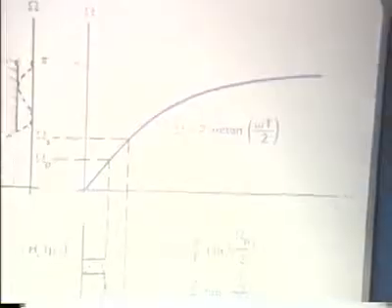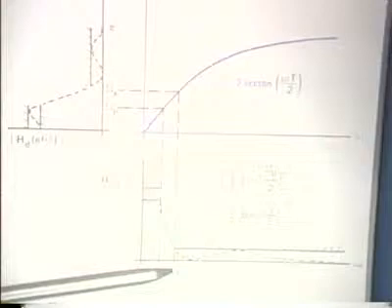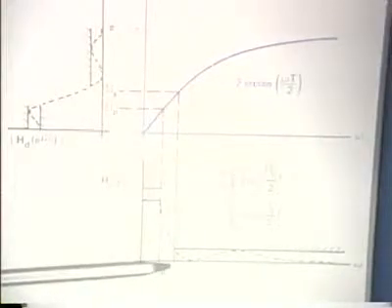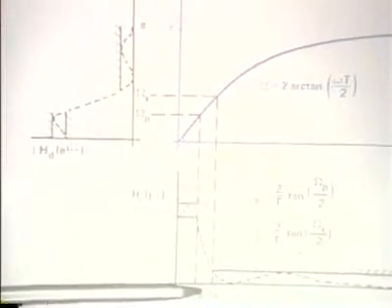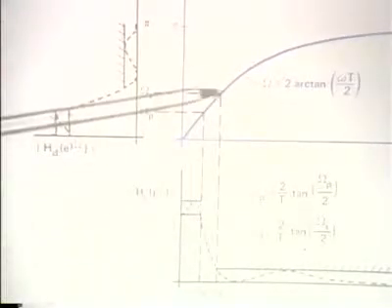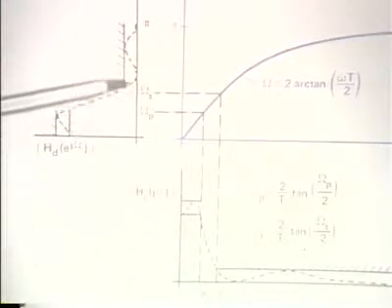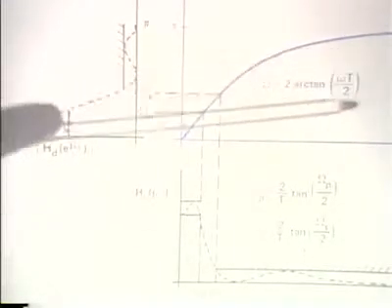So let's suppose that the continuous time frequency response looks as I've shown here, with a passband cutoff frequency and a stopband cutoff frequency. If this were mapped through the bilinear transformation to a discrete time filter, then this cutoff frequency would fall over here, which is related through this curve, and this cutoff frequency, the stopband edge, would be here, again reflected, it's these frequencies reflected through this curve.